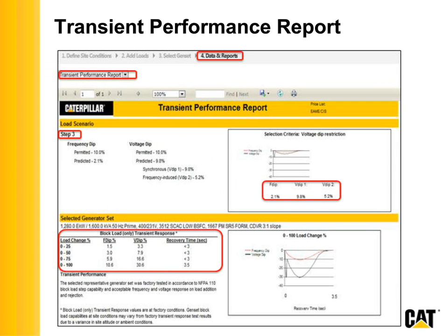It has better performance, and then that note's going to go away. And really all it meant is that with the standard voltage regulator, you weren't able to pick up full load in one step, according to NFPA 110, transient response. It's a North American spec.